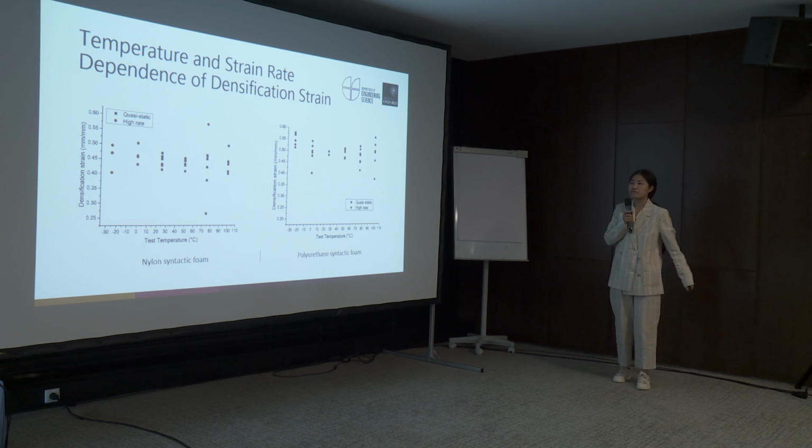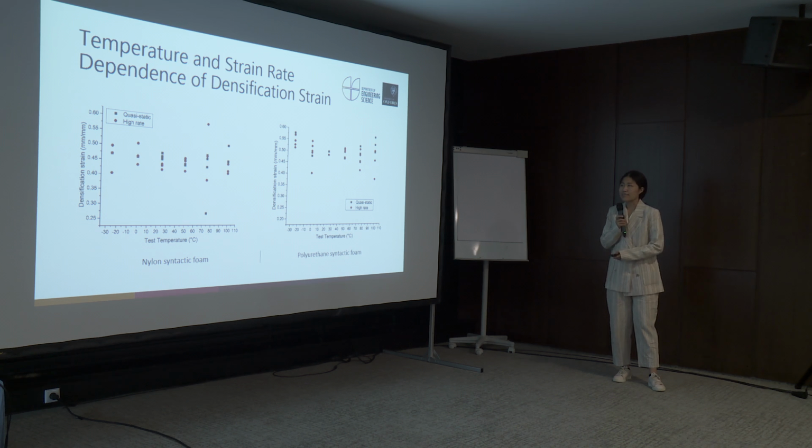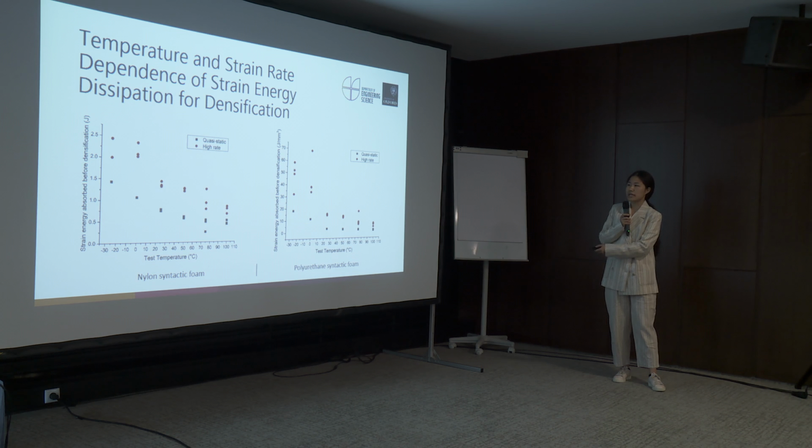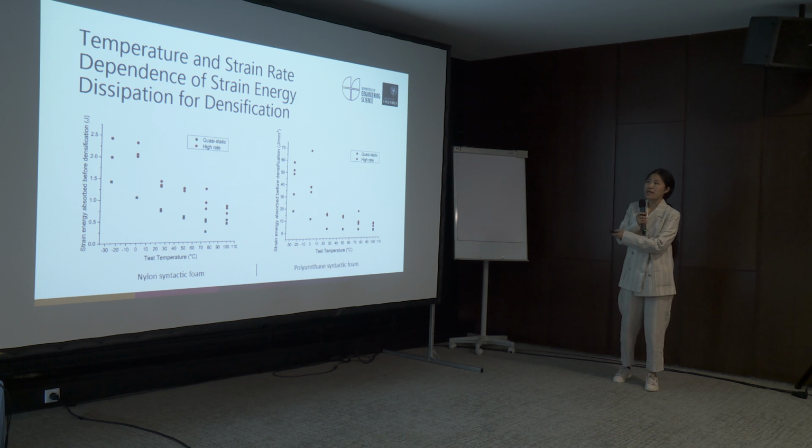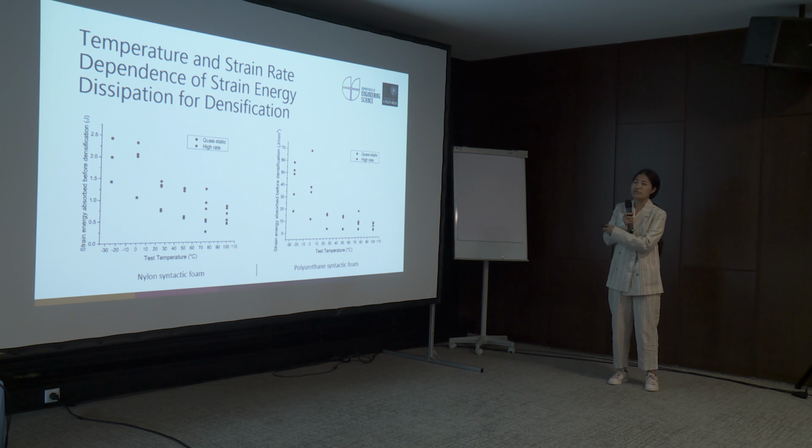It can be found that for the nylon and polyresin syntactic foams, regardless of the temperature and strain rate change, the densification strain is almost constant. Then this constant densification strain gives an increase of the strain energy dissipation efficiency for the densification, along with the increase of the test strain rate and decrease of the test temperature.